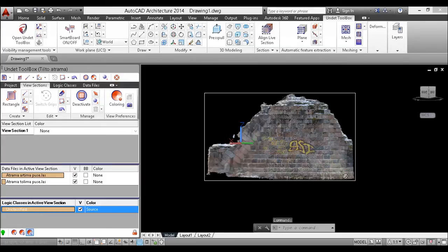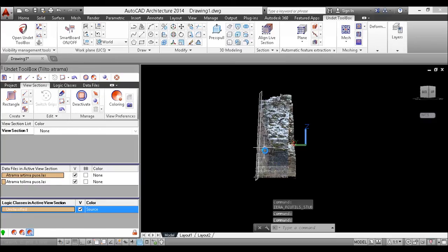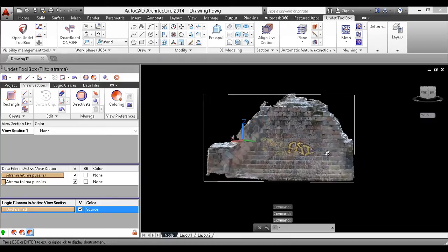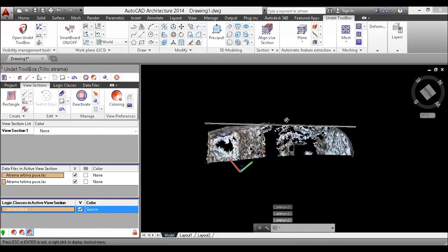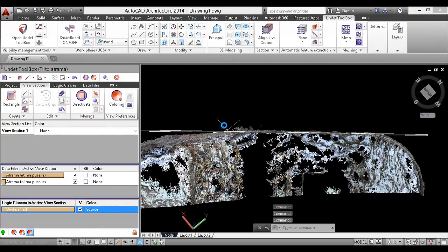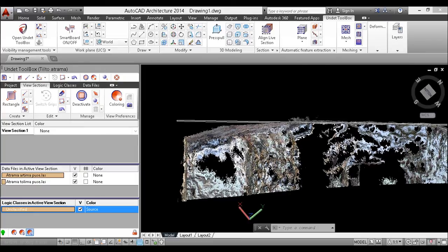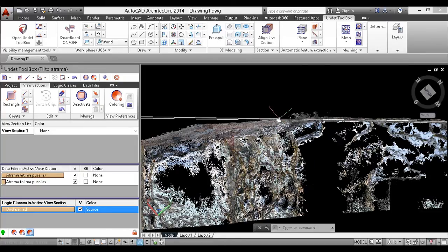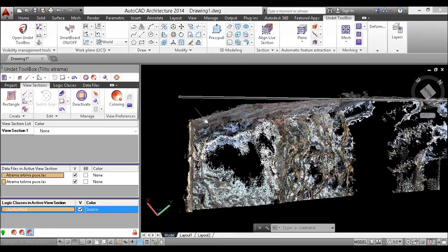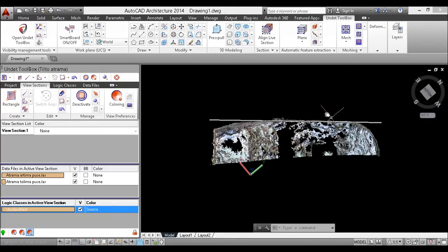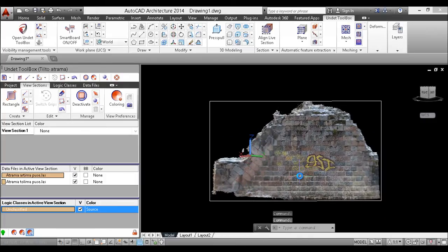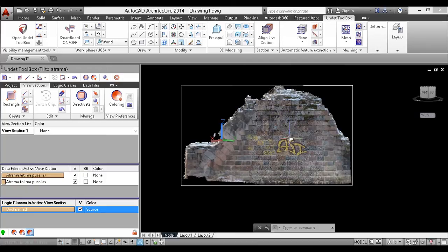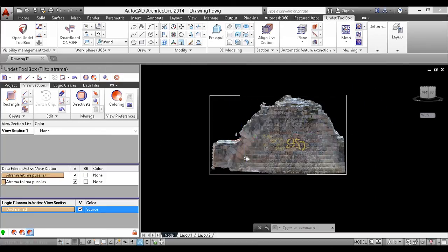So here is my orthophoto generated, and you see it is actual. It is leaning as well. It goes through the statistically calculated plane, and as I mentioned, my statistically calculated plane was within this region over here and somewhere over here, but I increased my region of the polygon because I wanted to have the entire picture. But the algorithm stopped suggesting exactly that size of the polygon, because it recognized that this is already another plane, as you see, and this is the third plane, and over here this is already a fillet edge. So this is a smart algorithm telling me that you should probably create several orthophotos if you would like to have actual dimensions in every one, but I'll use this only for texturing, so it is fair enough.